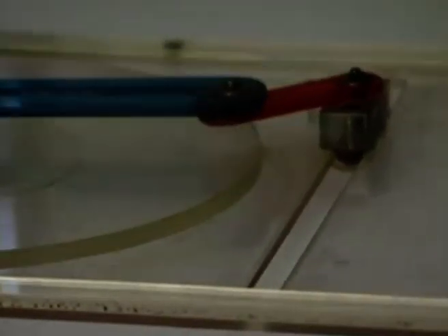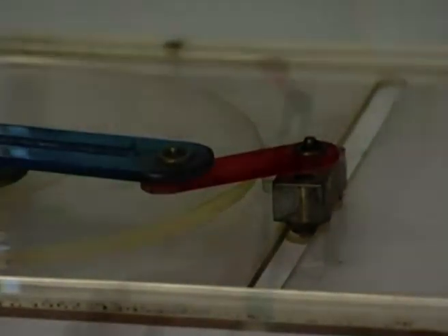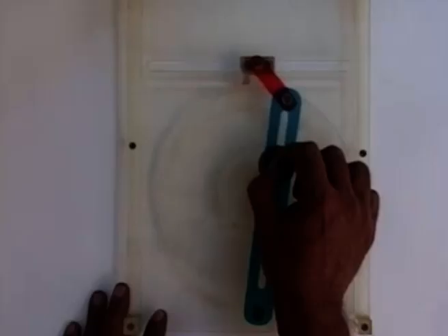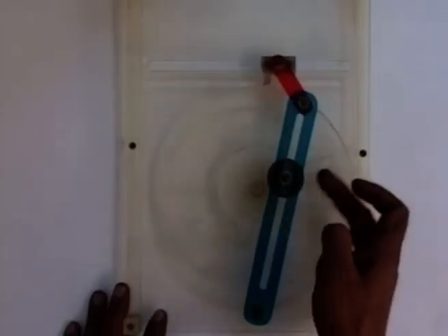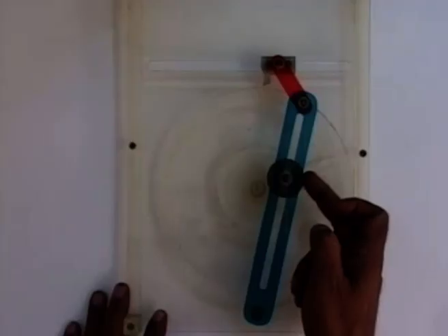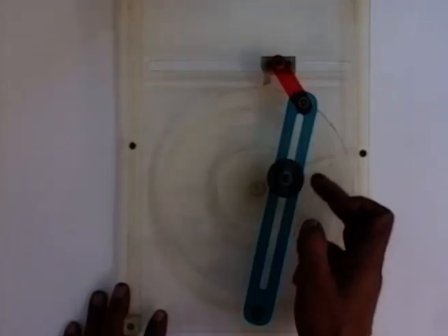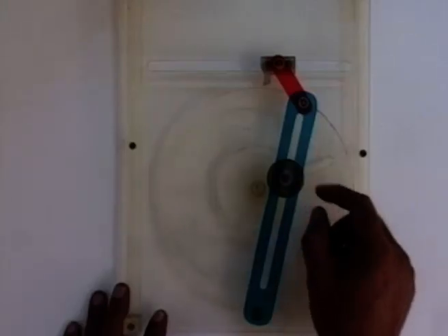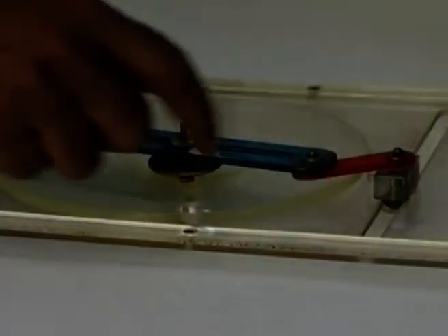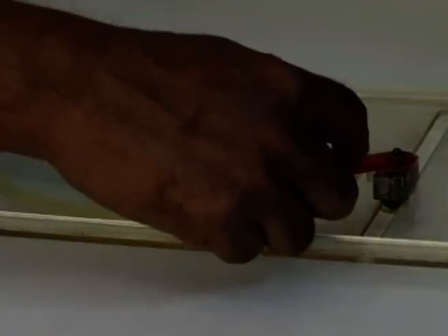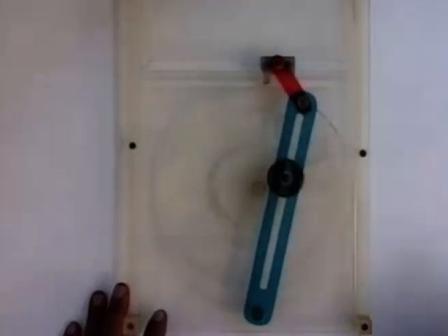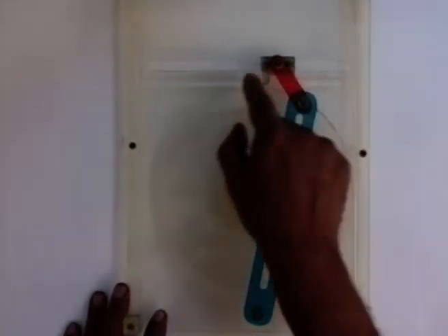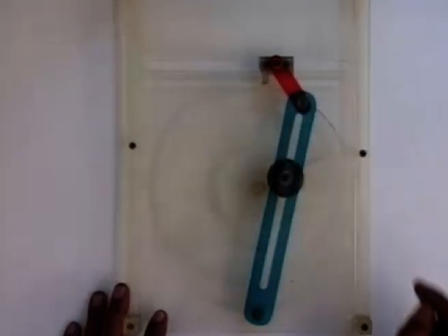This is the slotted lever quick return mechanism used in shaping machines. In this mechanism, there are 6 links. One is this rotating link, that is link number 2, fixed link is link number 1, this is link number 3, this circular block, which is hinged to body 2 at this point. And this is link number 4, the slotted lever, this is link number 5, and this tool holder or the tool is the link number 6, which has a prismatic pair in the body number 1.